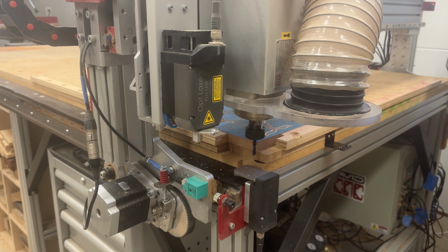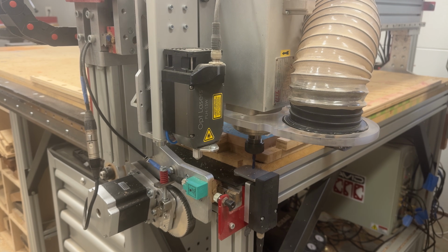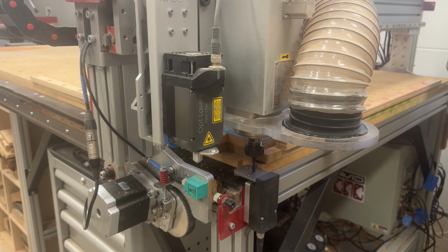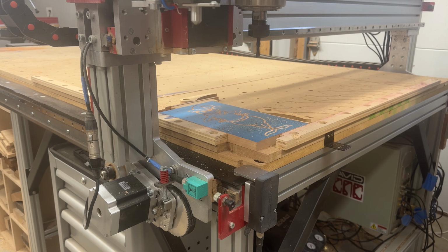So all we need to do on my machine, you hit a manual tool change load program, and what that's going to do is go over and touch the bit off the zeroing platform, and that's going to tell the machine what the height of the new bit is. On newer machines, you're going to have something called a probe touch plate, most likely, or you can just manually zero the tip of the bit to the machine.